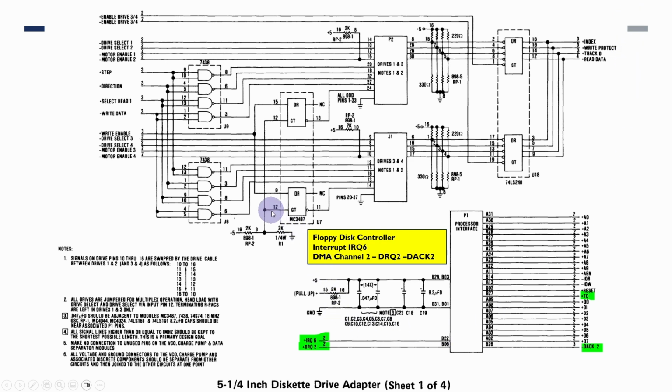Key thing here really is the floppy disk controller on the original PC was configured to use DMA, or direct memory access, and to cut a long story short, we had a lot of trouble trying to get that working, and in video 40 in fact I replaced DMA access after 10 videos trying to get it all working. Replaced DMA with programmed I/O, where the CPU basically just polls the floppy disk controller and doesn't involve DMA at all. And I will do a more detailed video, everything you'd ever want to know about floppy disk controllers,